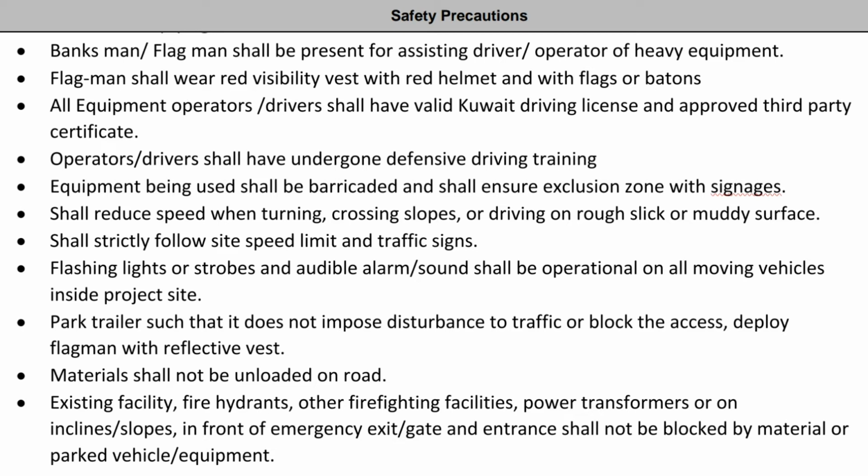Equipment being used shall be barricaded and shall ensure exclusion zone with signages. Shall reduce speed when turning, crossing slopes, or driving on rough, slick or muddy surfaces. Shall strictly follow site speed limit and traffic signs. Flashing lights or strobes and audible alarm sound shall be operational on all moving vehicles inside the project site.